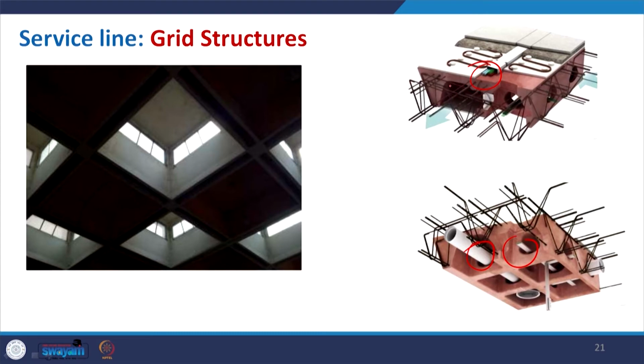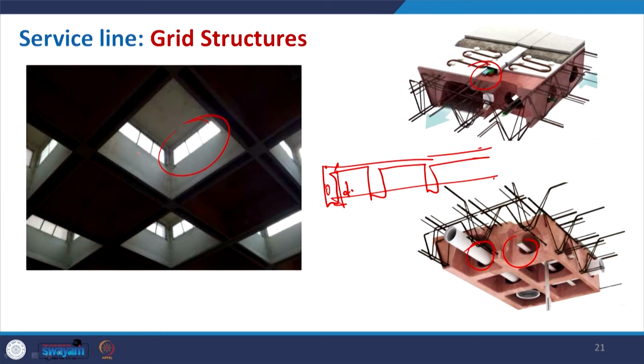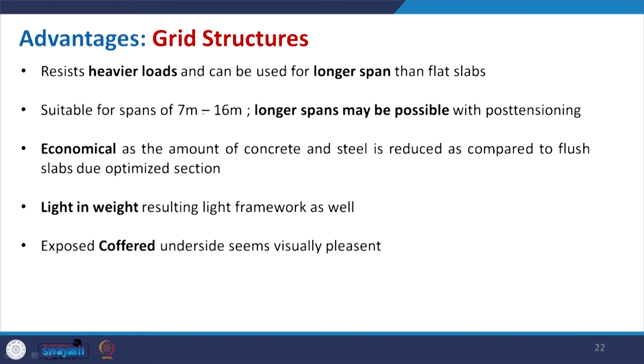So, the depth of the waffle slab that we referred to means whenever you have this kind of grid structure, this is the depth. Within that depth we are able to put all these services, so that it can give a nice look from the outside. At the same time, that can also be used to create some skylight for some public area where the large span is being covered. So, this is another useful application of this waffle slab.